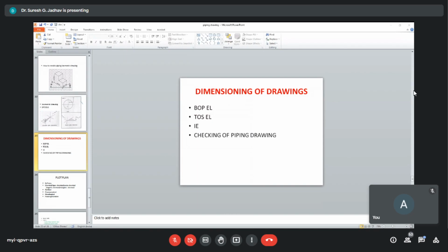Then correct identification on all lines in all views. Line specification changes, reference drawing numbers and files, correction of all dimensions, whether a representation is correctly made in line with the standard symbols or not.